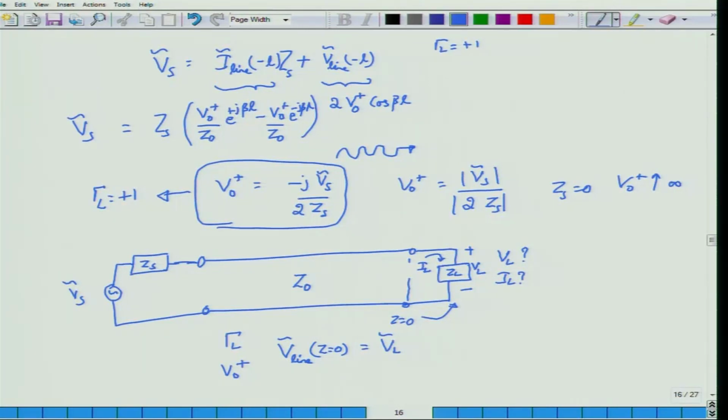So, to solve this problem, what we do is we develop the concept of an impedance at every point on the transmission line. What do I mean by this? At every point on the transmission line there is a certain line voltage, and this line voltage is a phasor of course. This line voltage will be there at every point on the transmission line, which will be the sum of forward as well as backward travelling voltage waves. Similarly, there will be a current phasor as well at every point of Z, and that would also be the sum of forward as well as backward travelling current.